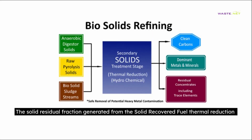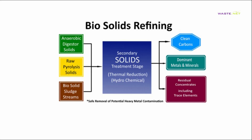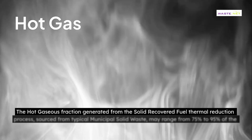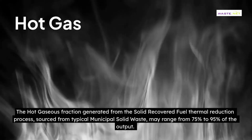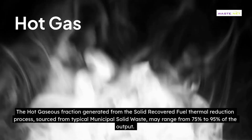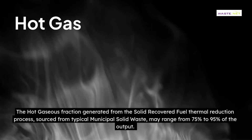The solid residual fraction generated from the solid recovered fuel thermal reduction process may only account for less than 5% of the total output depending on the consistency of the source feedstock. The hot gaseous fraction generated from the solid recovered fuel thermal reduction process, sourced from typical municipal solid waste, may range from 75% to 95% of the output.